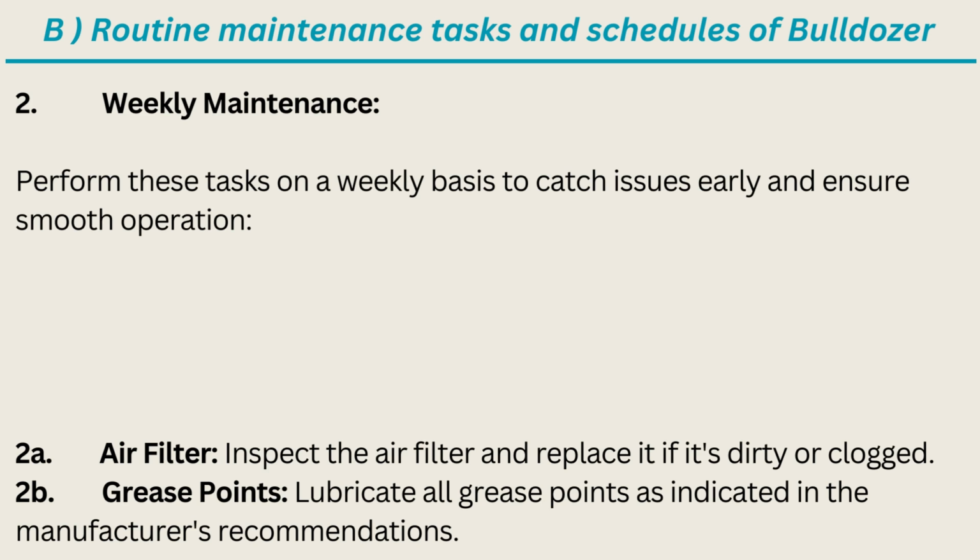2. Weekly maintenance. Perform these tasks on a weekly basis to catch issues early and ensure smooth operation. 2A. Air filter: inspect the air filter and replace it if it's dirty or clogged. 2B. Grease points: lubricate all grease points as indicated in the manufacturer's recommendations.